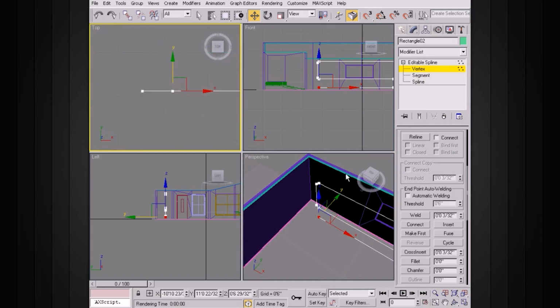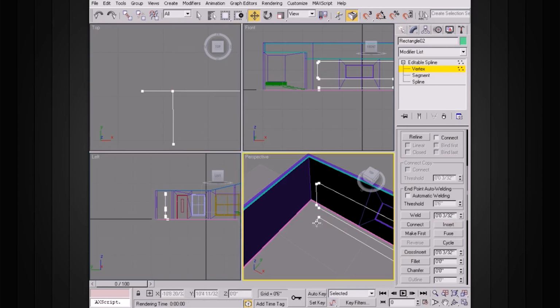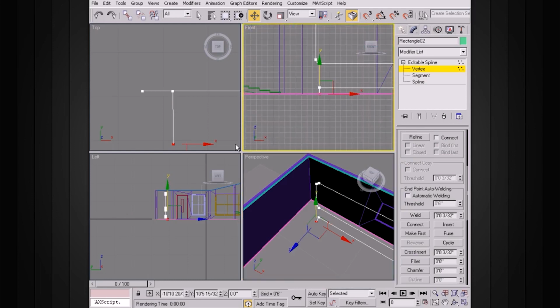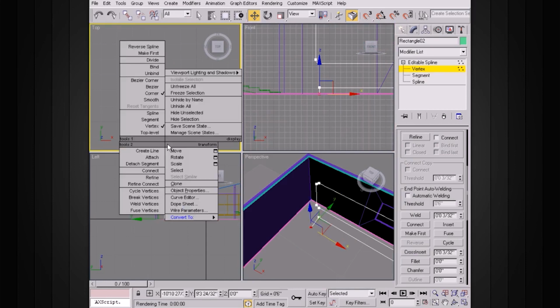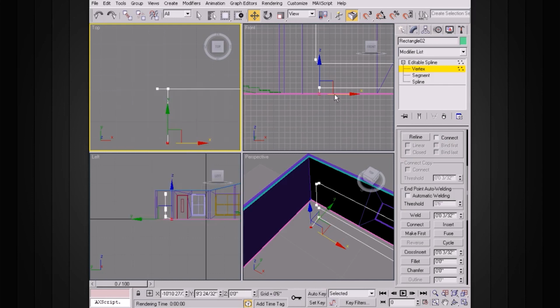So now what we want to do is come in and insert a new point, and we'll just pull this out. Undo that, click on here and pull that out. If you drag, it's going to make that a nice soft point once again, which is not what we want. So at this point I can grab this new vertex, and we want to line it up a little better with what we've got here. In the top view, pull it out straight a little bit more. You can right click on that and just make sure it has a nice sharp point.